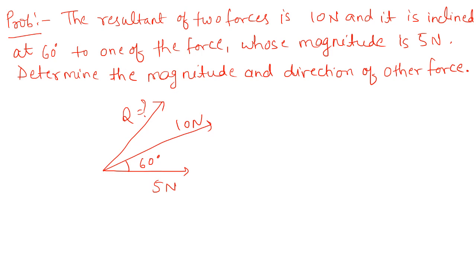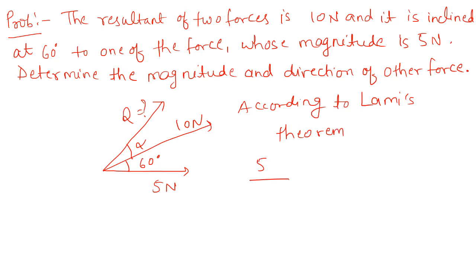So how can you solve this? Let's suppose this angle is alpha. Again you apply Lami's theorem. According to Lami's theorem, 5 Newton upon sine of the angle between the other two forces, that is sine alpha, and Q upon sine of 60 degrees, and 10 Newton upon sine of 60 plus alpha.